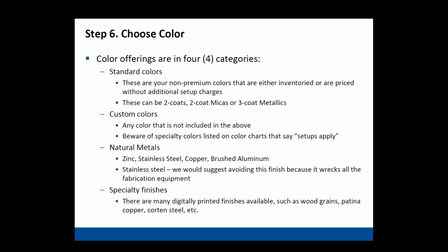Some of them offer multiple zinc types, but one of them might be more affordable than the other. And on all these natural metals, make sure you consult the manufacturer and find out what the sheet widths are, because some of them are only available in 1 meter wide sheets, and you don't want to get too far in your design and realize that the sheet goods are only available in 1 meter when you've designed everything around a 4-foot module or a 5-foot module.